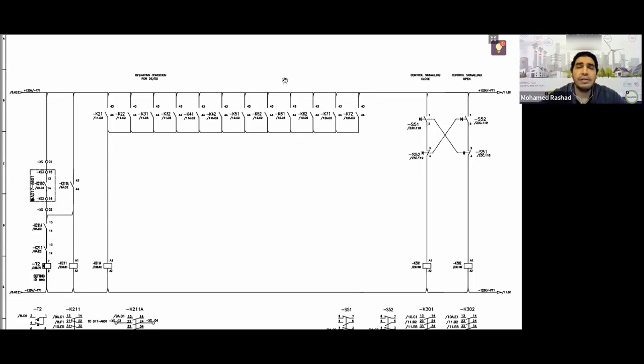All right, that's good. There is also a scheme available, for example, in Aramco Petroleum Company here in the Kingdom of Saudi Arabia, where if you give a close command or open command to any component in your panel, you cannot give a close or open command to any other panel in the same section, not in the entire GIS.